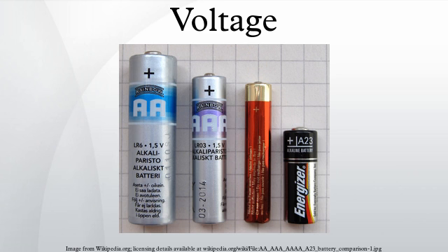The difference in voltage measured when moving from point A to point B is equal to the work which would have to be done, per unit charge, against the electric field to move the charge from A to B. The voltage between the two ends of a path is the total energy required to move a small electric charge along that path, divided by the magnitude of the charge. Mathematically this is expressed as the line integral of the electric field and the time rate of change of magnetic field along that path. In the general case, both a static electric field and a dynamic electromagnetic field must be included in determining the voltage between 2 points.